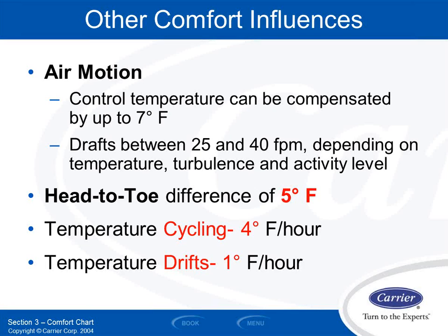If you have more than a 15-degree delta T between space temperature and discharge air, and you're following ASHRAE 62.1 as your ventilation standard and code, you're required by code to bring in 25% more outdoor ventilation air, right? You basically get an effectiveness multiplier added to your formulas of 1.2, which means you have a 25% penalty of air.